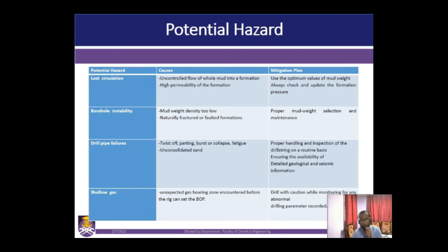Last but not least is the shallow gas. Unexpected gas bearing zone encountered before the rig can set the BOP. Drill with caution. The mitigation plan is drill with caution while monitoring for any abnormal drilling parameter recorded.